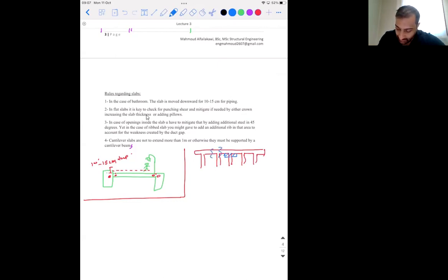Let's take a section here, section elevation, yeah? So if we have this column head, we're gonna have steel all over here. That's a way of doing it as well. Because if your shear capacity is exceeded, then you're gonna have punching shear. Punching shear is basically the shear that if you take a pen and stab a paper, it would rip it. That's kind of punching shear, like that.